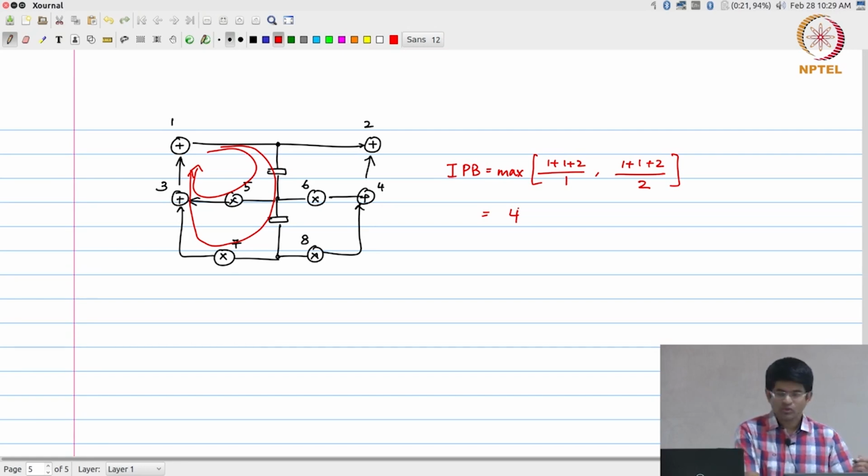So now it looks like my iteration period bound is 4, and I do have a loop that has only 1 delay element on it, which means that as far as that loop is concerned, I will never be able to bring the critical path down below 4 time units.